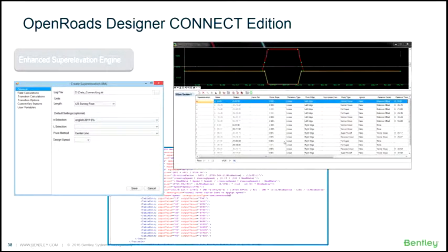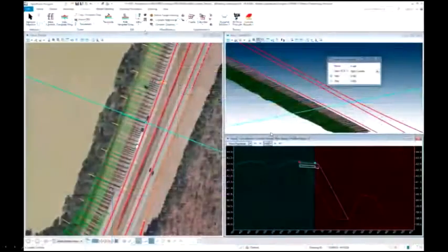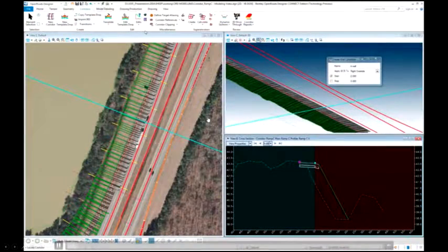There's no longer a need to have a programmer create new super elevation standards for your region or area. This can all be configured directly within this XML file that feeds the dynamic super elevation view within the application.